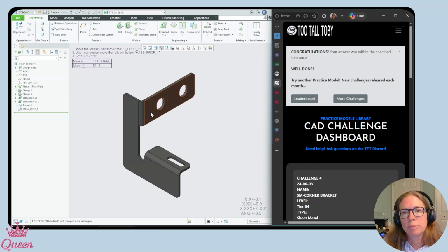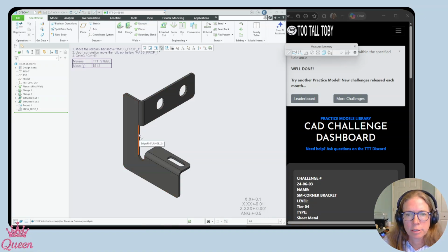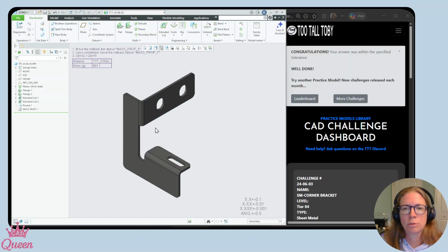Had to dig in a little bit for the bend option here. And while I could have measured the length of how long that edge initially was and had it come back 67, I used an embedded datum plane instead to extrude this down the 55.